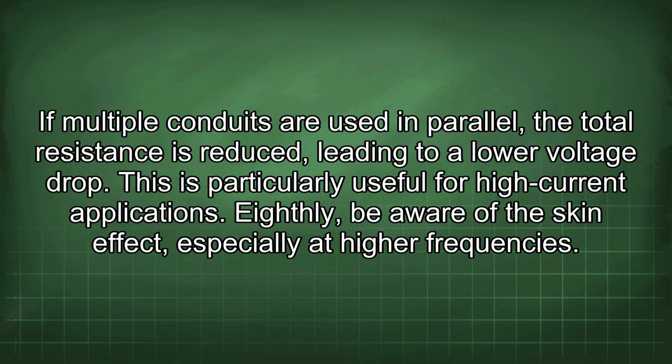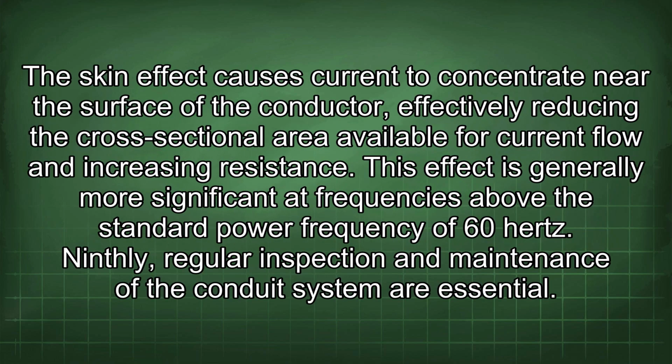Eighthly, be aware of the skin effect, especially at higher frequencies. The skin effect causes current to concentrate near the surface of the conductor, effectively reducing the cross-sectional area available for current flow and increasing resistance. This effect is generally more significant at frequencies above the standard power frequency of 60 Hz.